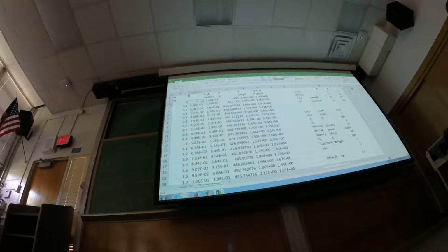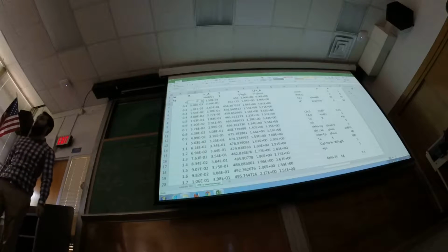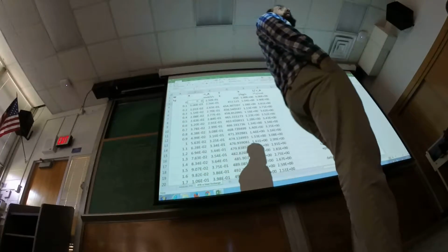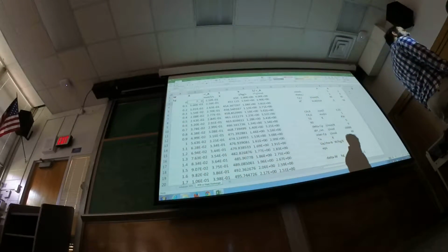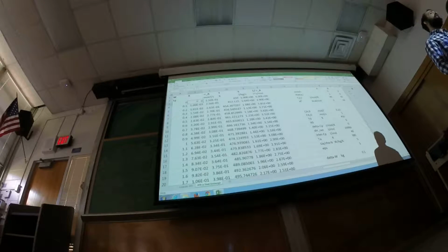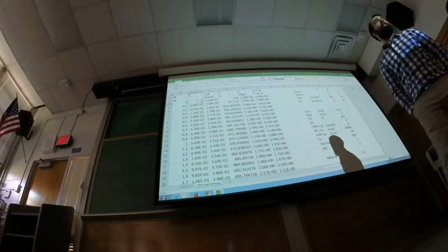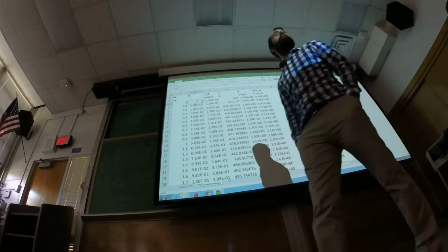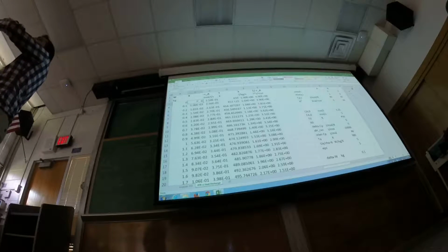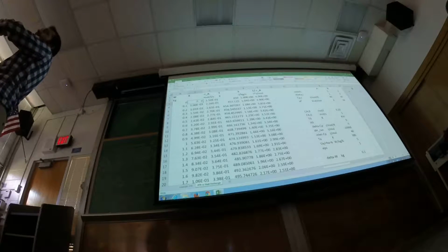Okay, so what do we expect? Is this an exothermic or an endothermic reaction? Exothermic. So what's going to happen to the temperature along the bed of the reactor? Yeah, but now I'm cooling it with something at 300, way colder than our inlet temperature. Our inlet temperature is 450. My cooling fluid is 300. So you think it'll go down first and then go back up. But it could also go up and then back down.